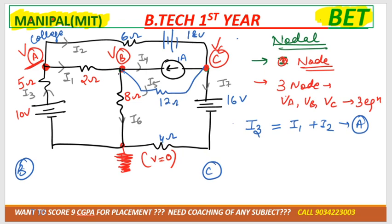At node B, I1 is entering, I4 is outgoing, and I5 is also outgoing, right? Now for node C, looking from the top, I2 is incoming, right? I4 is also incoming, going inside, and I7 is leaving. So I2 plus I4 is equal to I7. Got it up to here? Okay, now see, I3 is moving from which node to which node.